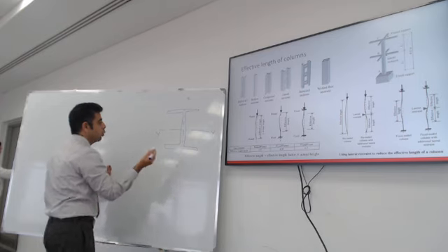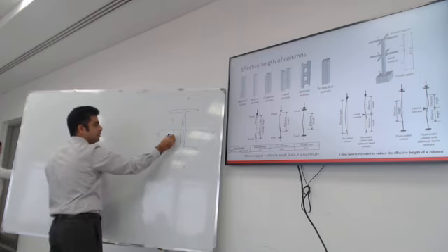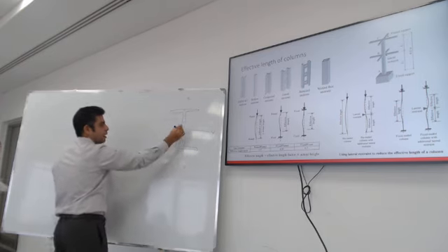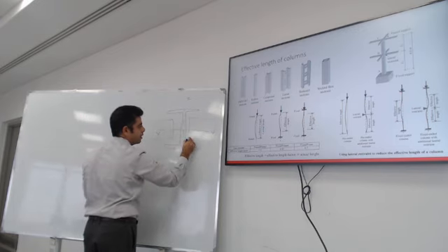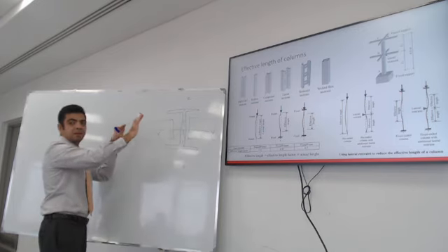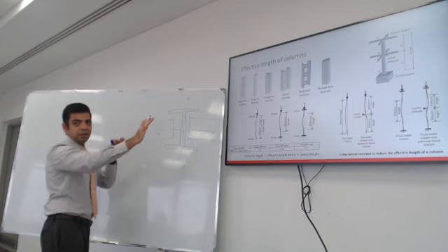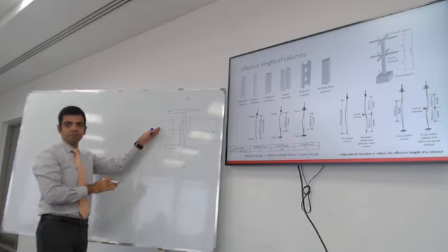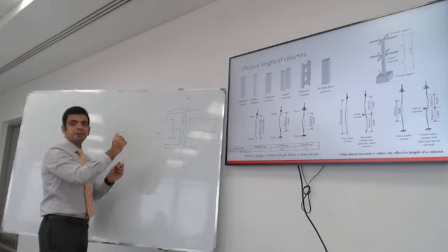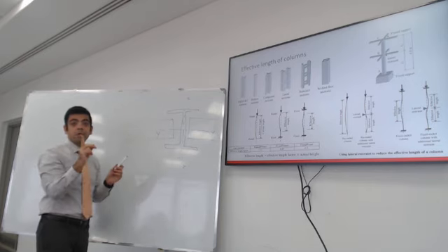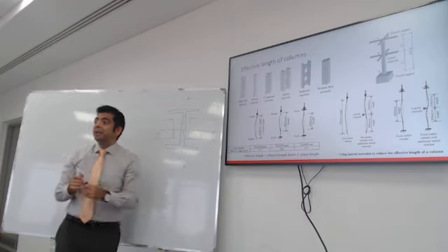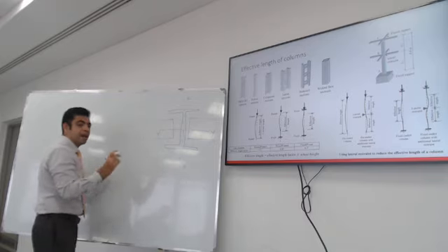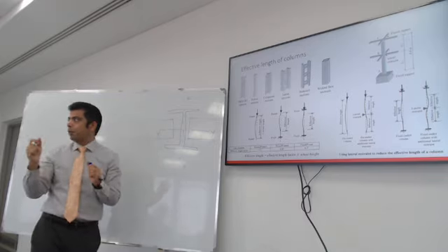Okay. So what if there was a beam in this direction, bracing the column this way? So it's from the bottom till that beam. To Y. To that beam. But if I took it about Z, so it's from the bottom till the top. No, that's the thing. Is this column braced about Z or about Y?